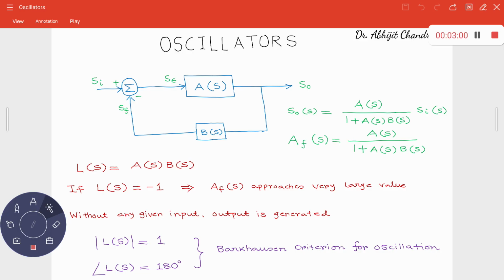The coupling capacitors in series were considered a short circuit. The bypass capacitors in the shunt, parallel path were assumed to be open circuit under certain frequencies. Eventually, the effect of the capacitors was not present, and in the back network there were no frequency sensitive elements.